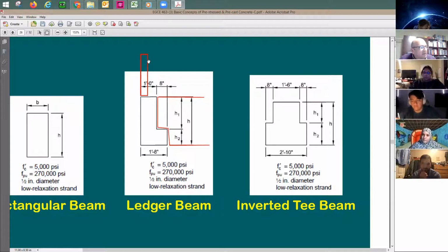And in a case like this, they don't use this, and instead they use cables. It's going to be tension cables. Use a cable at 4-inch on center, for at least 30 inches. Right.